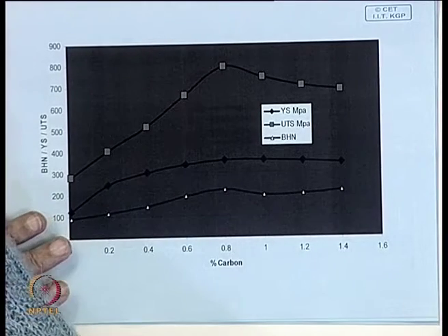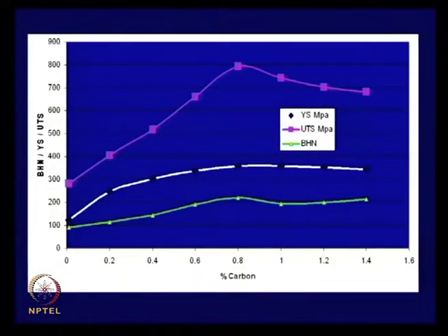I think next diagram here, this typically shows, whatever I talked about, you look at this with carbon content. I took this data from handbooks for steel which are cooled at a very slow rate, annealed steel, and this axis gives Brinell hardness. So, look at this part, the hypoeutectoid steel, it is very strongly dependent, but thereafter the change is not much.